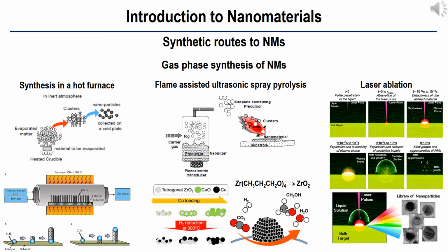2. In heterogeneous CVD, the solid is formed on the substrate surface, which catalyzes the reaction, and a dense film is formed. In order to form nanomaterials, several modified CVD methods have been developed. Gas phase processes have inherent advantages, such as an excellent control of size, shape, crystallinity and chemical composition, and relatively easy synthesis of highly pure materials with multi-component systems.